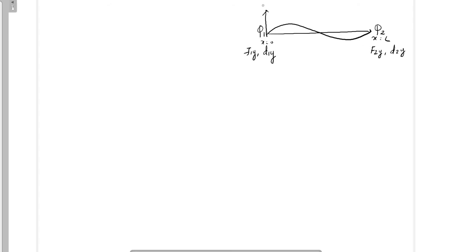The y displacement is referred to with v. If you have the displacement in the x direction, we normally refer to it as u. As in the case of the bar element, you assume the displacement function as u equal to c0 plus c1x plus c2x squared. Here the displacement is a vertical displacement, so your assumed equation should be in the form of v. So this is the beam element.